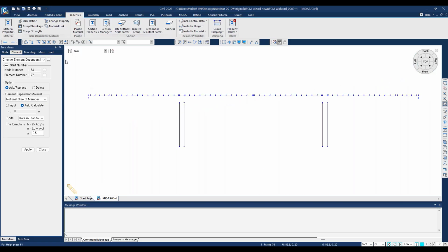this girder from the beginning. I can use this one from the beginning until the end. Then after selection of this, you hit apply. Then the software will calculate the section property of these sections of the beam elements we defined, and each section will have its time dependent property, because they don't have the same size.